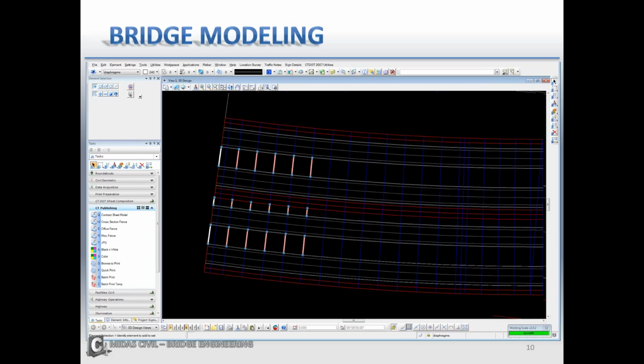And what I'm going to do is bring these nodes into Midas. I want to import the nodes versus importing the actual elements because the tub girder is a little more complicated, in particular because of the cross frames being in the interior and exterior. If it was an I girder, it would be a little bit easier to import the elements as well, but because it's a tub girder, it's a little more difficult. Now that being said, you can do it. I just prefer to import the nodes.